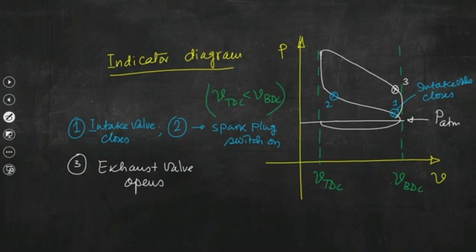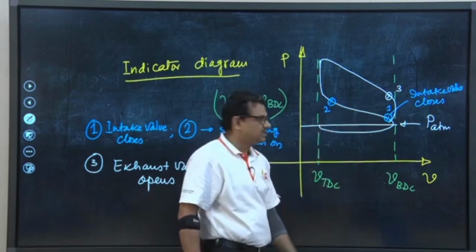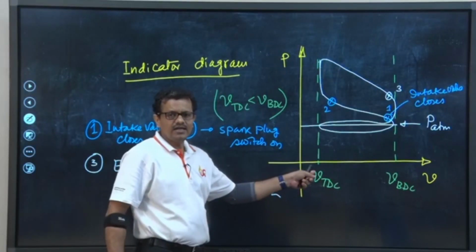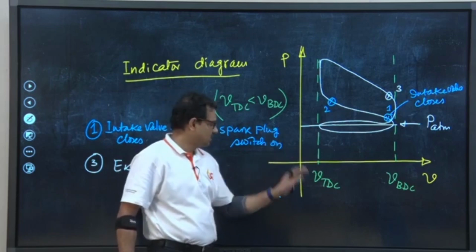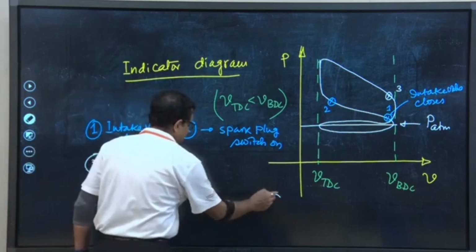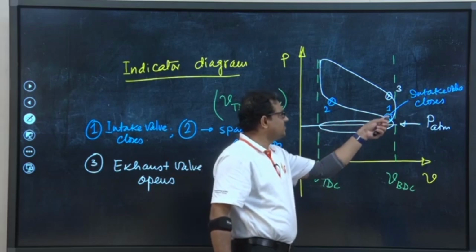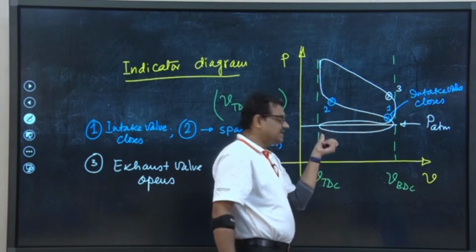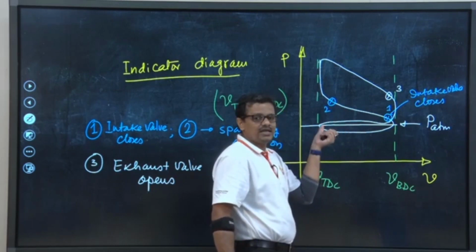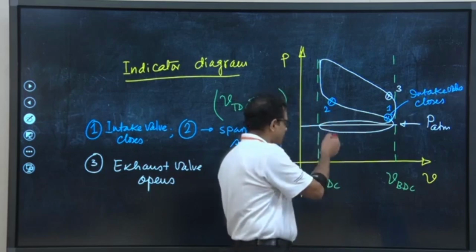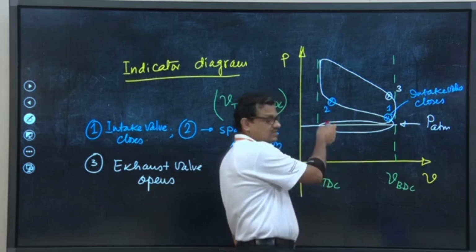And then piston is coming from BDC to TDC, the combustion gases inside the cylinder will go out from the chamber, and then when piston is coming to TDC, ideally we should open the intake valve, but what is done in reality, you know that exhaust valve is remaining open, but ideally intake valve will again open when piston is at TDC, but in reality intake valve is allowed to open when piston is yet to reach TDC.